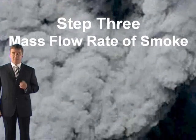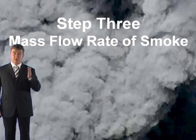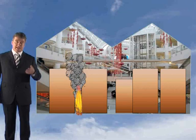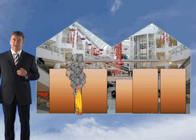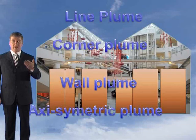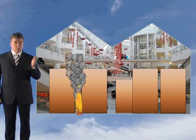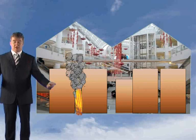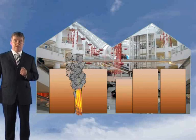Let's move on to step 3 now. Step 3 is determining the mass flow rate of the smoke. Now again, we firstly need to establish whether this is classified as a simple plume or a complex plume. Now in this case, the design fire is located in the reservoir where it's going to be extracted, so it's a simple plume. Now we have to decide which model to apply. Is it a line plume, is it a corner plume, wall plume or an axisymmetric plume? Well, as the stores are going to be located everywhere, we have to look at worst case, and the worst case is the one that will give you the worst mass flow rate, which is an axisymmetric plume. In other words, in the centre, because it's got air coming in from all angles. So the model we're going to apply is the axisymmetric plume.